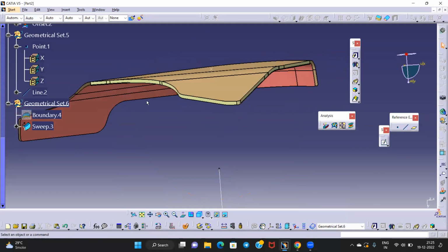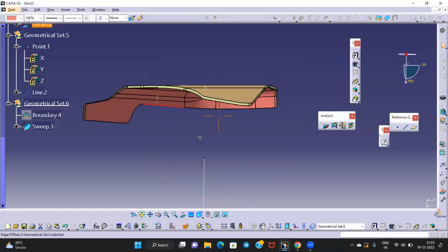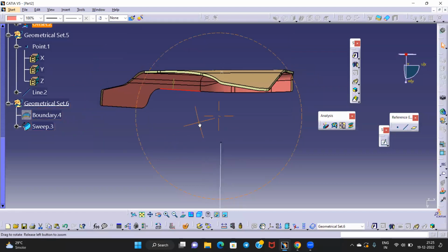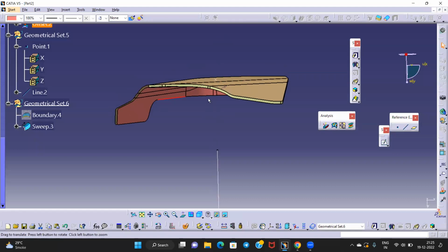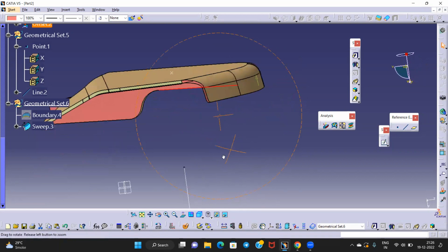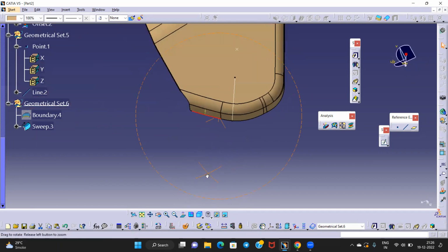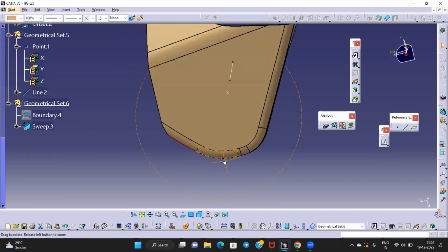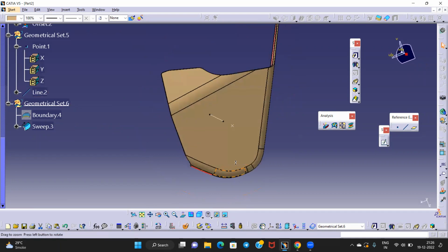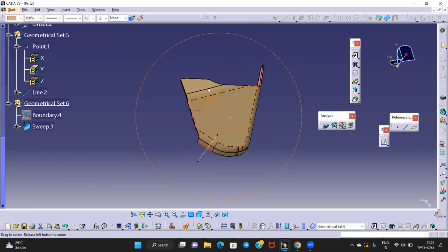Now this surface doesn't need draft direction because this is parallel to face because it is going to sit like this, right? So this cavity will be here, core will move here. So this flat is also fine. Okay, so this flat from this edge, it is not perpendicular. See, it is at 0 degree. But here we need a draft direction.